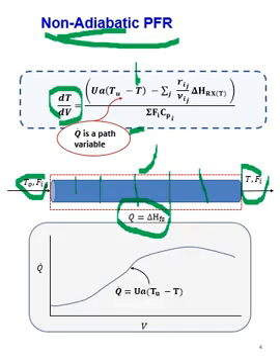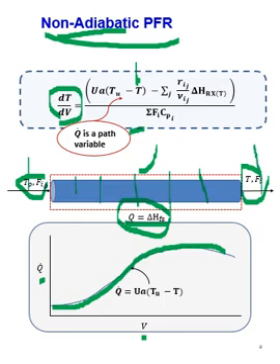However, what I must realize is that this rate of heat transfer I can actually draw as a function of the volume along my reactor. At each little step I will have a different rate, but the total will still be equal to the total amount of heat transfer due to the overall change in enthalpy from the inlet to the outlet state.